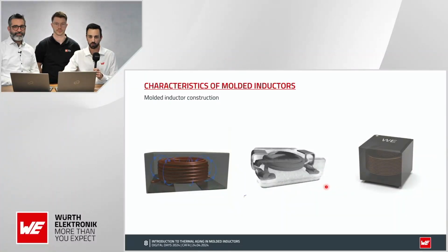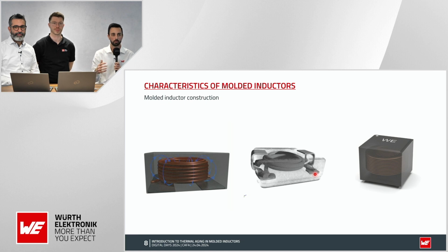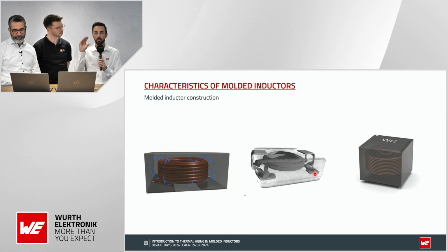Yeah. No. Because we do the soldering before we do the core. I think this will be helpful. The first thing we do to build this molded inductor is to do this winding, this coil, and then we do the soldering to the lead frame.